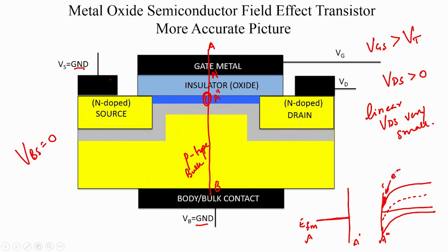That is the channel region, shown in blue in the figure, and this gray shaded region is the depletion region. It is basically all the acceptor ions that were exposed and are compensating for the charge applied on the gate metal, along with the free electrons. So, this is the picture of what is there along this cut line.